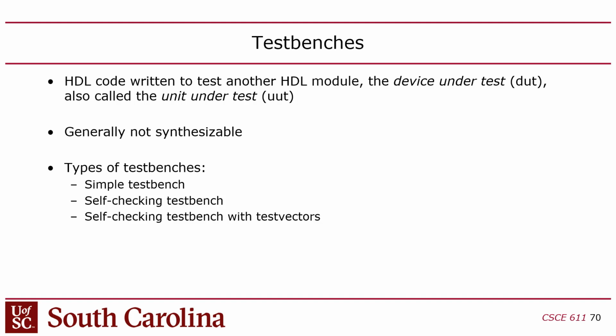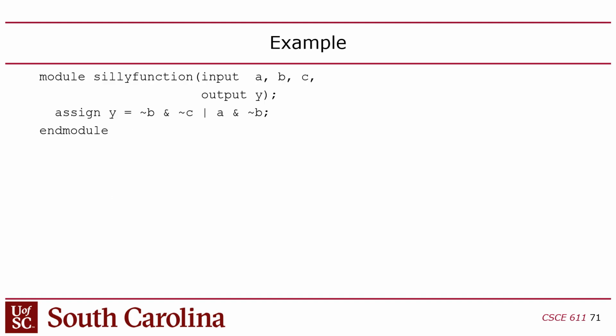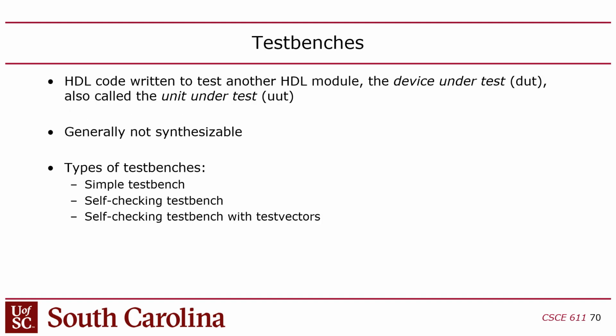And also, it can be self-checking. The test bench could check automatically the output from the design you're testing, and it can print an error message if there's a problem, right? As opposed to you trying to look at the waveforms, which is tedious, right? So, of course, you don't have to have the test bench do that. You can just have the test bench drive the inputs. It doesn't have to check the outputs, right?